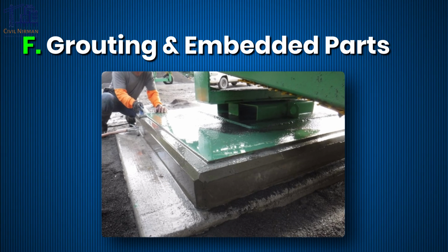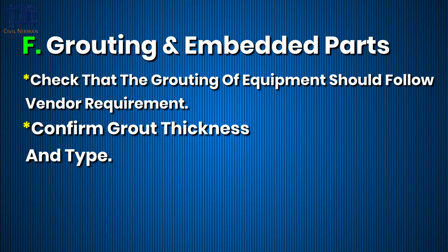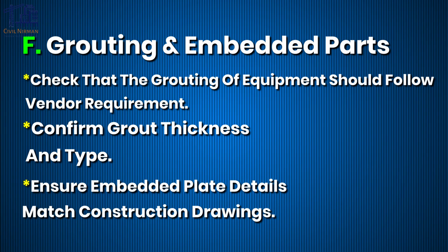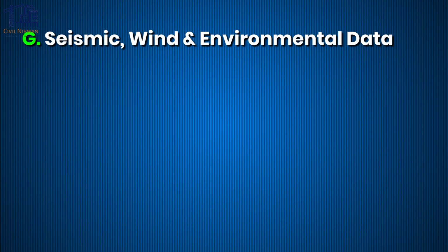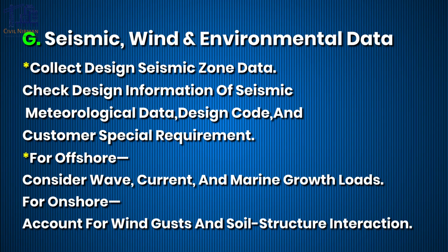Next important point is grouting and embedded plates. Check that the grouting of equipment follows all your project standards and vendor requirements as well. Confirm the grout thickness and its type. Ensure that the embedded plate details match the construction drawings. Next important part is seismic, wind and environmental data. Collect design seismic zone data. Check the design information of seismic, meteorological data, design code and customer's special requirements. For offshore, consider wave, current and marine growth loads. For onshore, account for wind gusts and soil structure interaction.